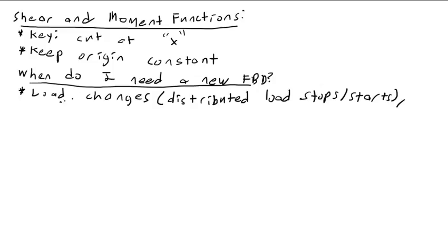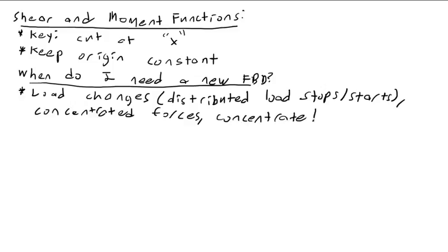A concentrated force, if you have a concentrated force, that is an instantaneous change in the load. Concentrated forces, concentrated moments, supports, etc. Essentially, anywhere where there is a discontinuity in the load, when you're developing a moment function or a shear function as a function of x, you are going to need a new cut.